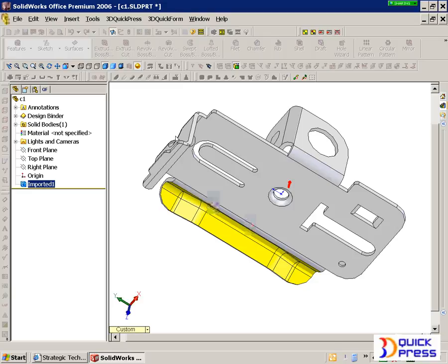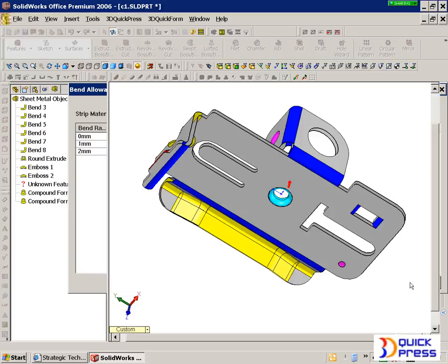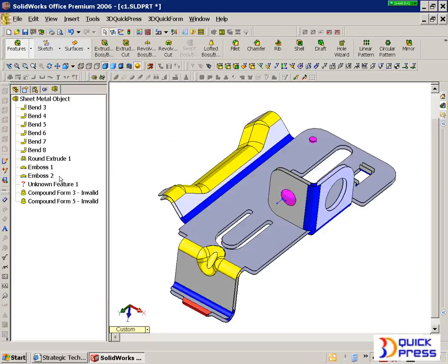Of course, all the bend compensation can be adjusted per feature. Let's find those features first, which is quite unique. So it does feature recognition. It gives me a bend report. It highlights the areas it can unfold. As you can see on the left, we now have an unfold manager. So instantly we get features that we can unfold. And yeah, there's a few that we can't unfold.